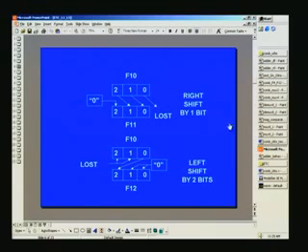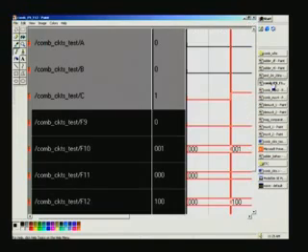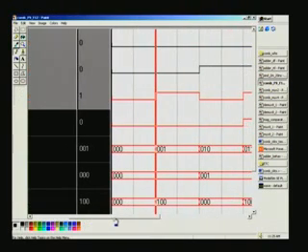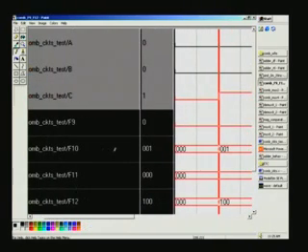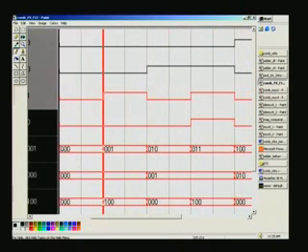So let us see that once again. F11 is right shift by 1 bit. So what should be shifted? It is actually F10 which is being shifted. That is the input we have seen. So let us see what happens here. If you right shift here, this 0 will get lost, and the vacated bit will always be filled with 0. So it continues to be 0. So that's why the result is 0 here.